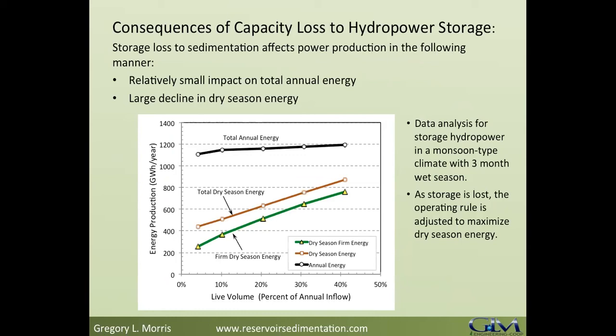So it depends on how the reservoir is operated. If the reservoir is normally maintained at a high level, for instance, a water supply reservoir in a moist climate that is drawn down only occasionally, then you would probably not experience that type of problem very early. But if you've lost 50% of your capacity, regardless of where you are, by that time, you're probably looking at problems.